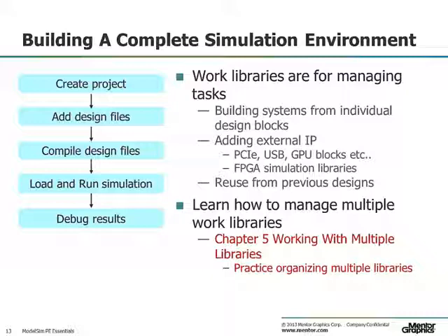Chapter 5 will allow you to practice creating and using multiple libraries. You can learn how to use the ModelSim.ini to reserve and preserve those library mappings that make the environment portable from one environment to the next. You can create mappings to as many individual libraries as you need to accomplish your verification tasks.